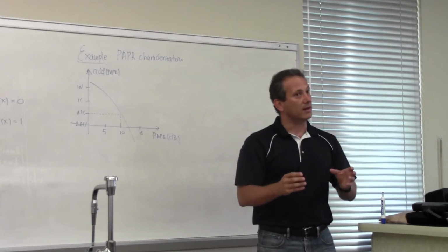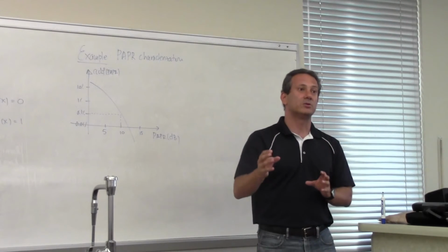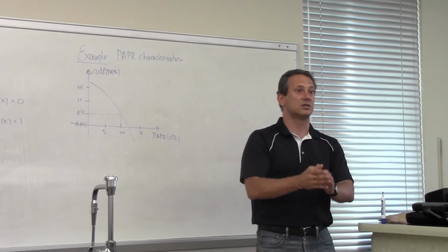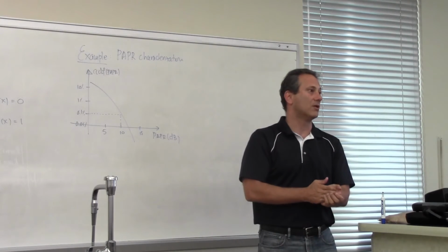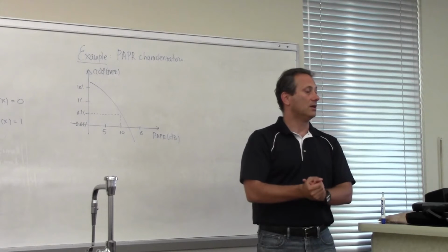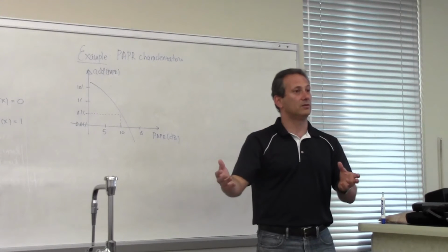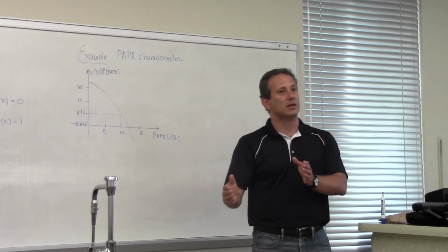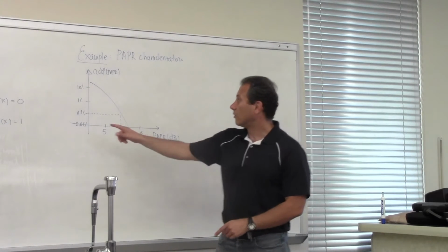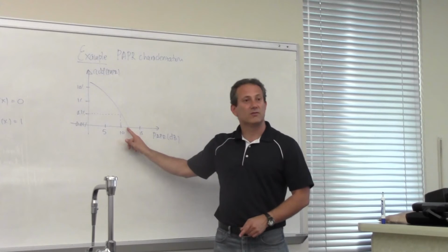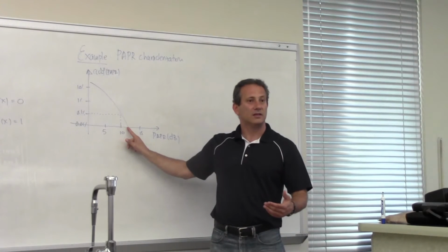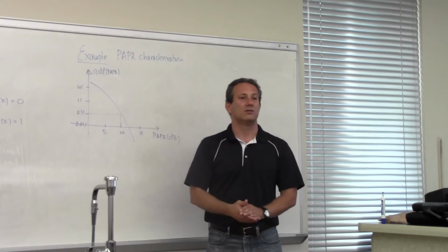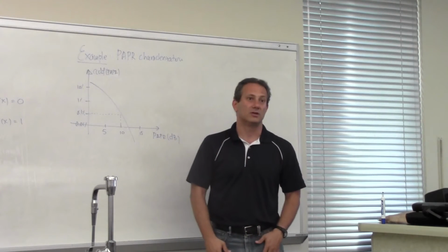So if I design my link, and I'm shooting for 0.1% reliability, my link needs to be able to handle the losses associated with 80 millimeters per hour rate, right? If I want to increase my reliability of the link, and let's say I want to design for 0.01%, then I have to find for 0.01% what is the rain rate exceeded in that case, and then I have to design my link to handle these kind of losses associated with this particular rain rate.